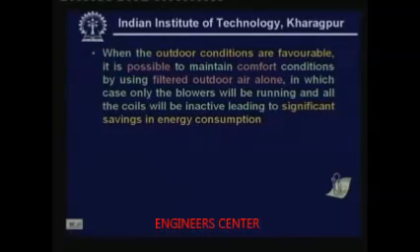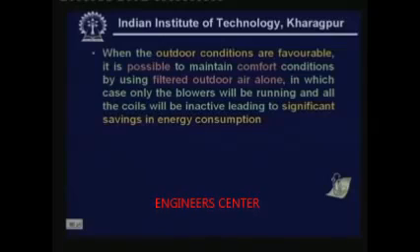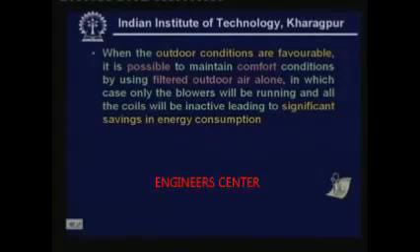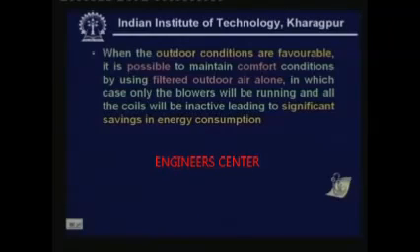And when the outdoor conditions are favorable, it is possible to maintain comfort conditions by using filtered outdoor air alone. That means you can switch off everything and just run the blower. Okay. In which case only the blowers will be running, and all the coils will be inactive, leading to significant savings in energy consumption. Okay. So when outdoor air is cool, let us say, then you do not have to use any cooling or dehumidifying coils or anything, just run the blower and use full outdoor air and provide comfort.